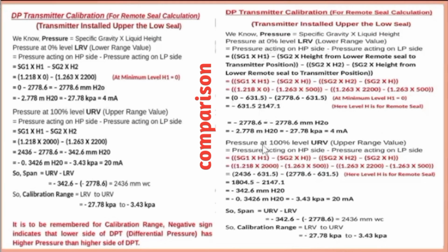And the LRV and URV: here LRV is minus 27.78 kPa, here is also minus 27.78 kPa. Here is a minus sign. And also you can see the URV is the same, minus 3.43 kPa, and here is also the same.